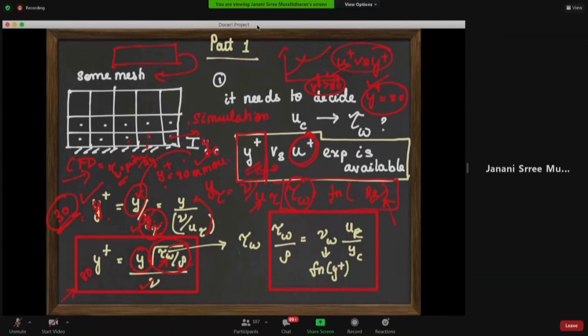If there is a difference between the y plus that the code calculates and what you calculate, you have to find a midway, keep refining the mesh or expanding it, trial and error, till both match.